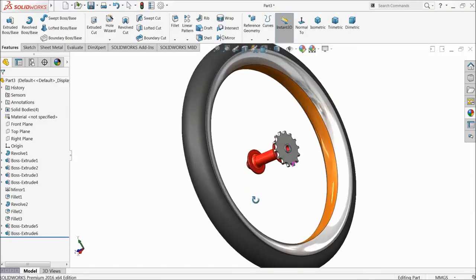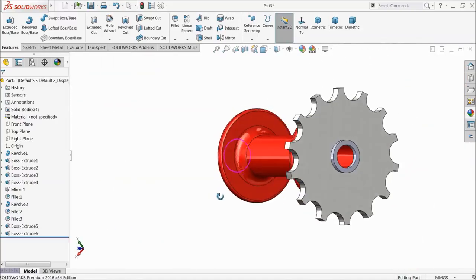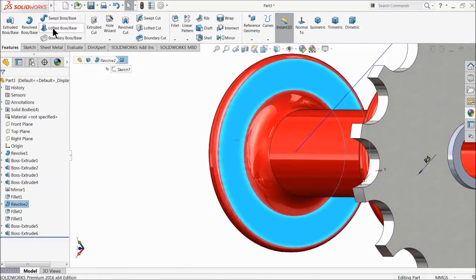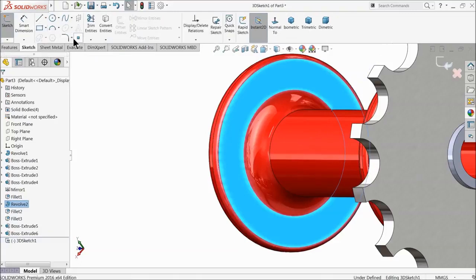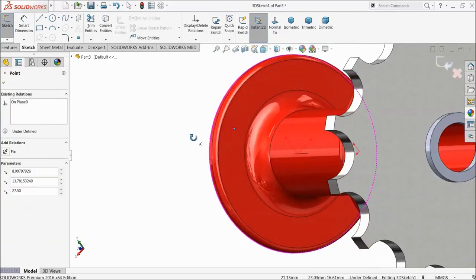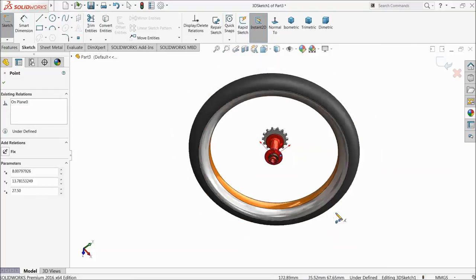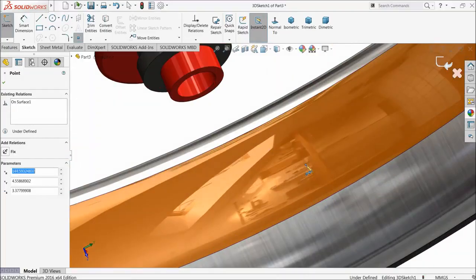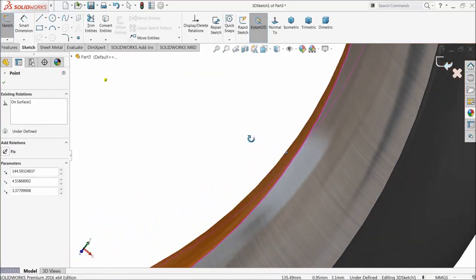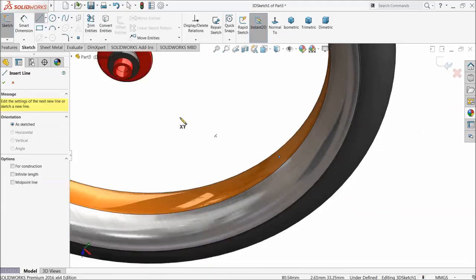Now here let's create the bicycle tire spokes. Select this face, 3D sketch. Select here star point and put our star here in the mid of this line, and we will put one star just a little. Okay, now choose here line.